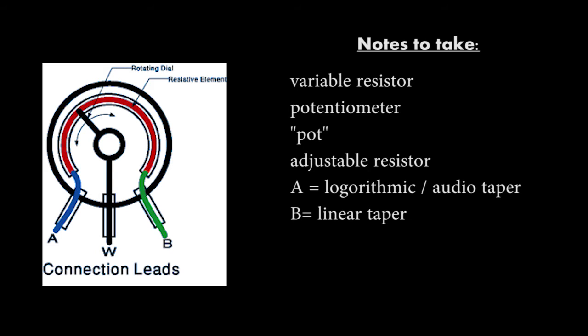That's a fixed resistor. There's two metal legs, a little bit of resistive material that goes from one end to the other, and then it has a third leg with what's called a wiper attached to it that can cheat its way into that fixed resistor wherever it wants along that path of resistive material. This changes the amount of resistance from the center leg to either of the outside legs, but it doesn't change the resistance between the two outside legs.